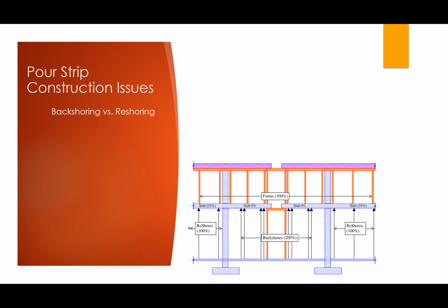That's why right here I put the slab, and then in brackets I put 25%, because in principle, those slabs in your typical bays have available capacity that could be used to support the wet weight of concrete above. And you'll see shortly that indeed they are used, just not necessarily here, but they could.